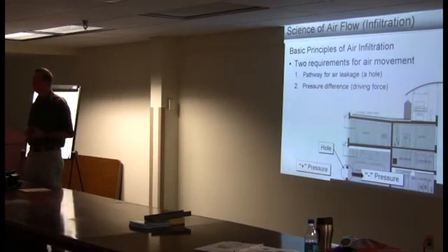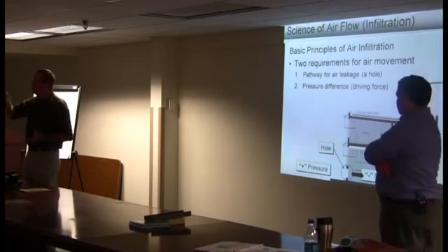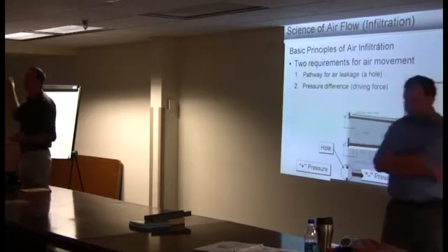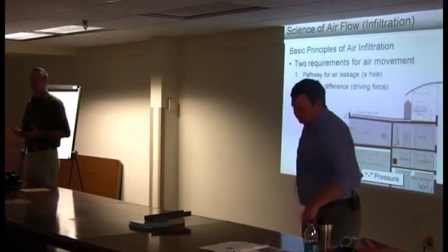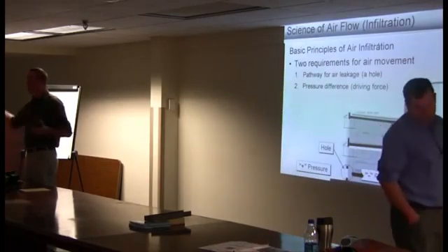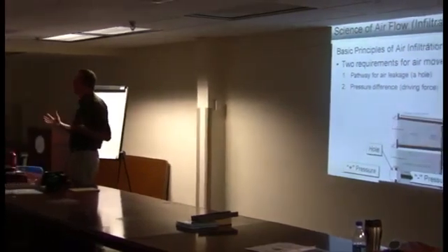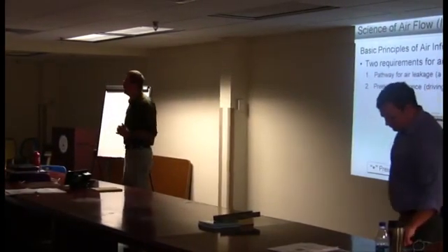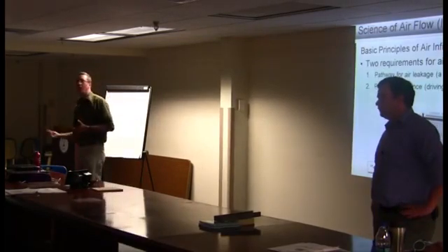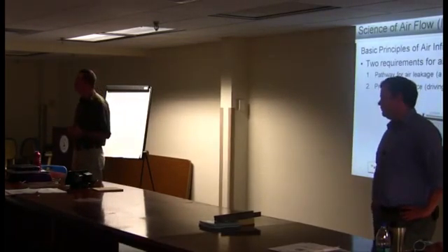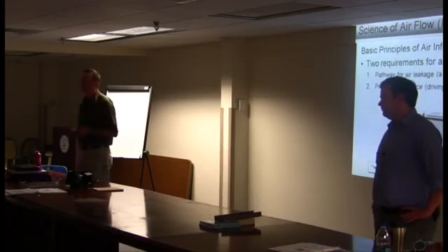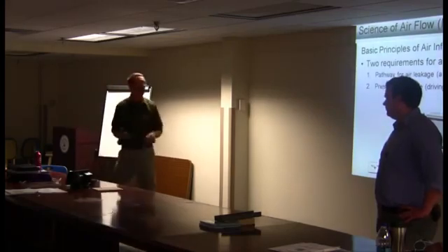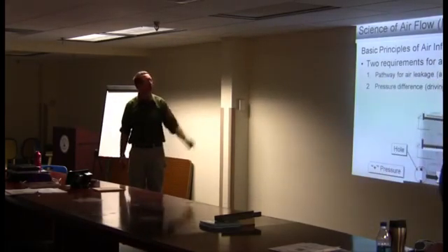So in commercial buildings in particular, this is something we want to strive for. And now there are places within the commercial buildings we want to pull air out, right? We want to exhaust air from toilets and things like that, janitor closets. But in general, we would rather put back more than we pull out. So our building is slightly positive in this climate, or at least neutral. We don't want our building to suck for a long time, right? To be under negative pressure, because that really could cause moisture problems. That causes air to come in from where we don't want it. So I'd say in general, think positive pressure on buildings. Think positive. All right, what are the other things?